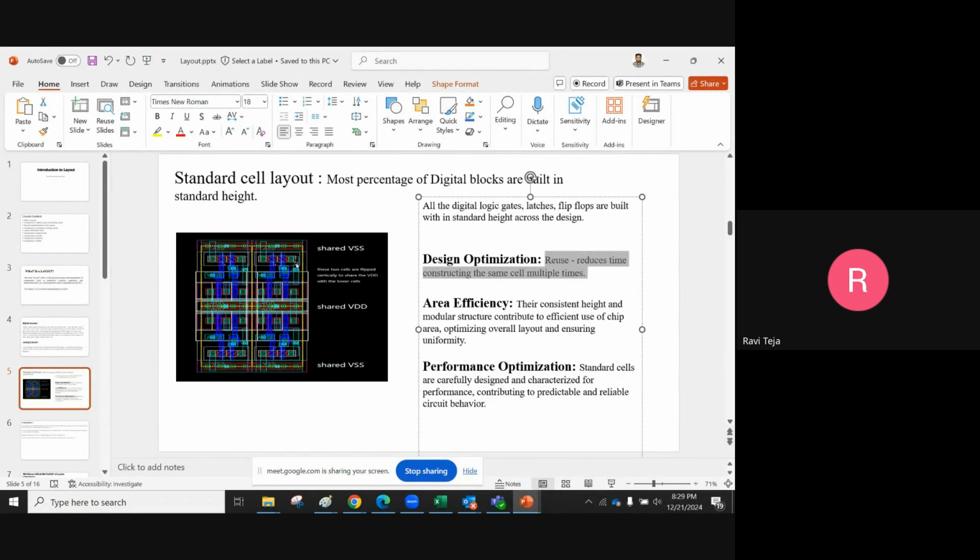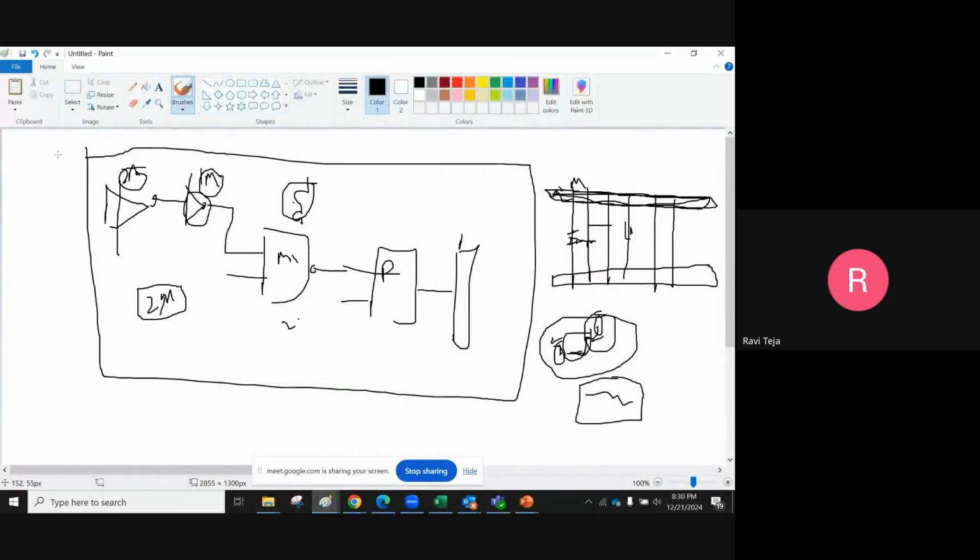Just to, what happens is if you build, okay, if you are using some 5 6 AND gates and you're using different sizes for different blocks, then one AND gate will have some separate circuit behavior and layout parasitics, and the other one will have different parasitics. But what the designer will assume is, so generally while they are doing some transistor modeling,